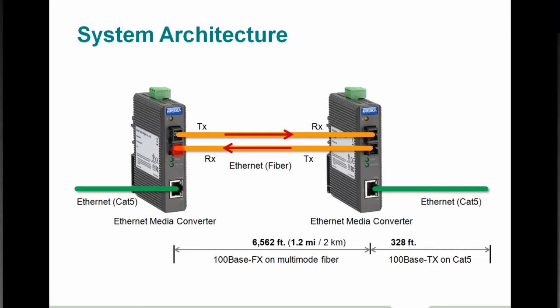This type of technology is the most commonplace. There are other technologies to carry full duplex, meaning simultaneous transmit and receive over a single fiber, but doing so requires more complex, higher performance, and more expensive optical transceivers utilizing a technology called wavelength division multiplexing.